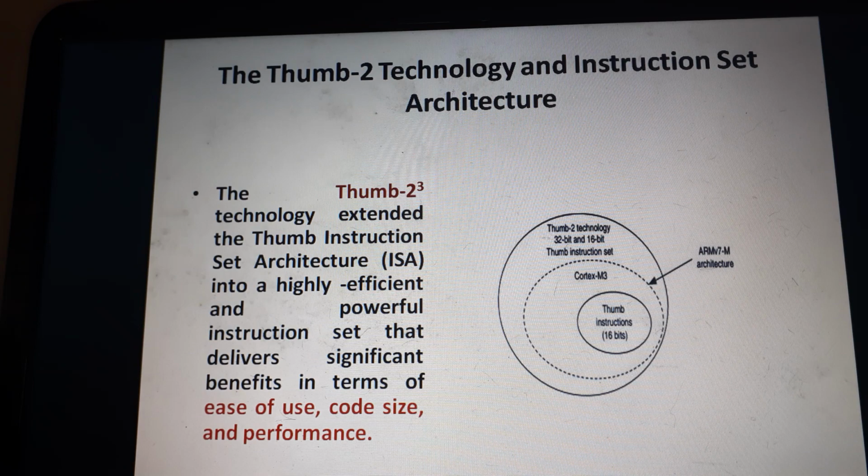The method of writing code in a traditional ARM processor is writing code using a few instructions of the ARM instruction set and a few instructions of the Thumb instruction set. Whichever job or operation is possible using Thumb, use Thumb instructions to implement that part of a program.